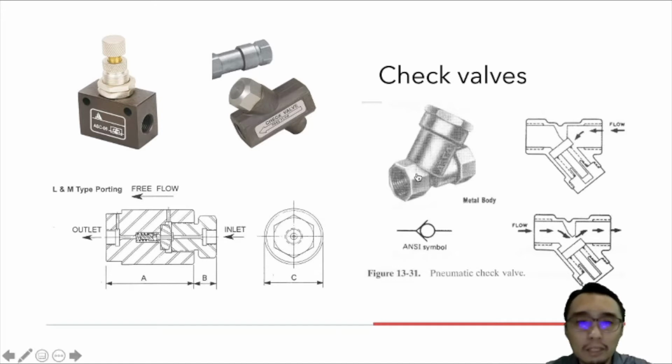As shown in the schematic views, the disc seals before reverse flow is established, thus avoiding fluid shock on reversal of pressure differential. Although the design here is metal, lightweight plastic body design with fittings suitable for plastic or metal tubings are also available.